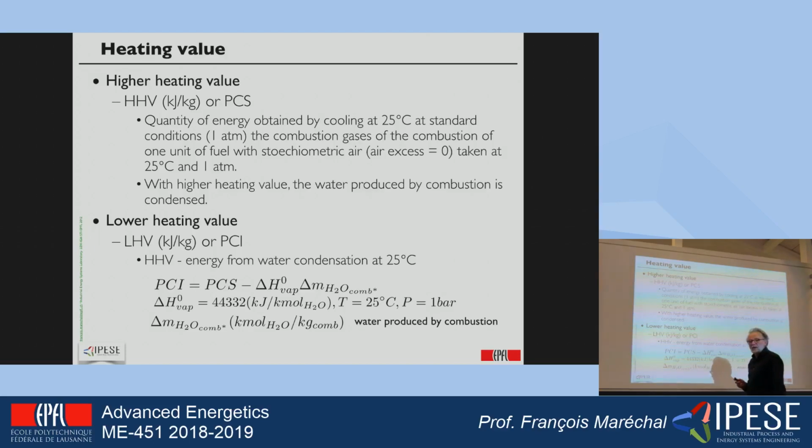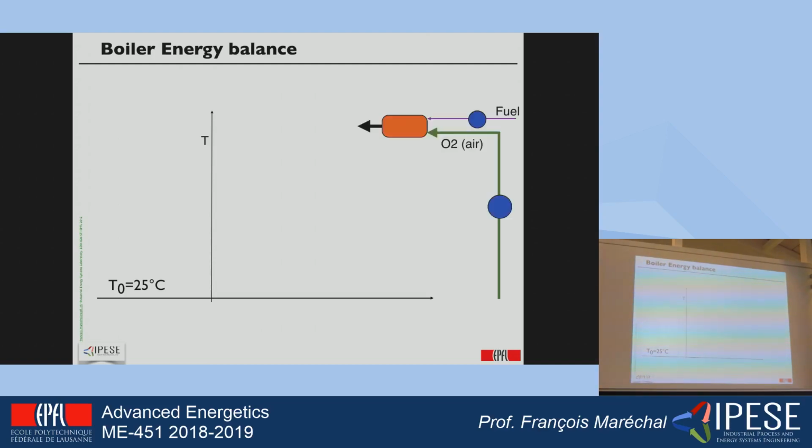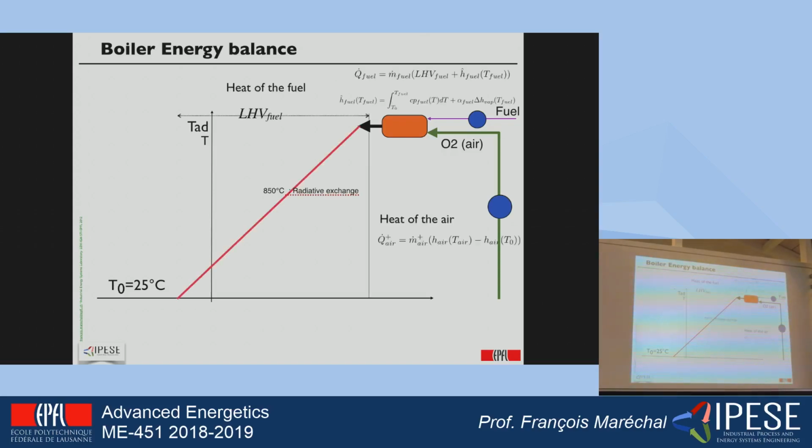From there, we can look at what temperature enthalpy profile we will obtain when we do a real combustion in a real system. Okay? In a real system, I will not be at 25 degrees C, so I will not be in standard conditions. So in addition to accounting for the lower heating value, I will have to account for the contribution of the state of the fuel, the temperature at which it enters the system.